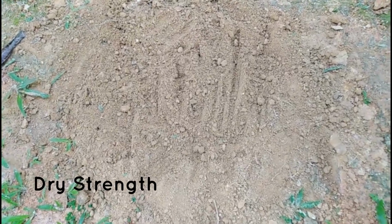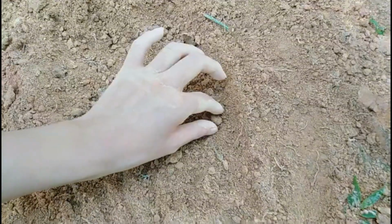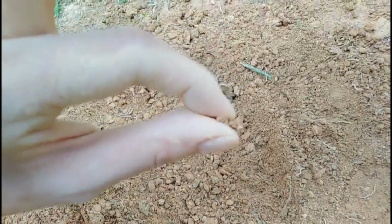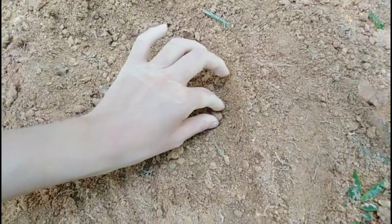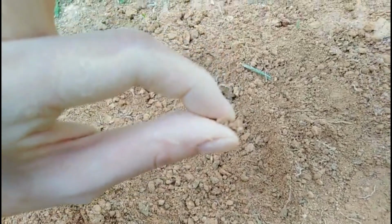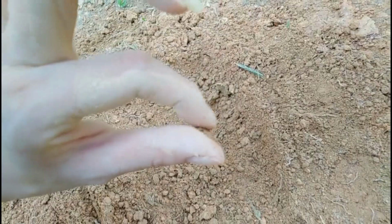For the dry strength property, I take some lumps formed in the soil that are completely dry in sun or air and press them between my thumb and forefinger to observe the resistance of the lump to breaking. I can feel that the lump requires finger pressure to break, so I can describe the strength of this soil as medium, and this soil contains silt with a small amount of clay.